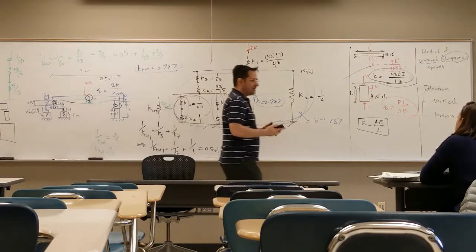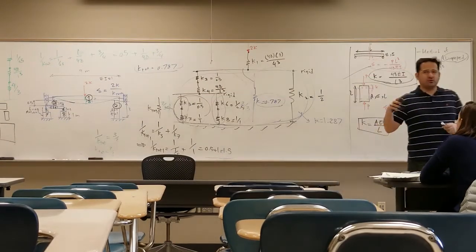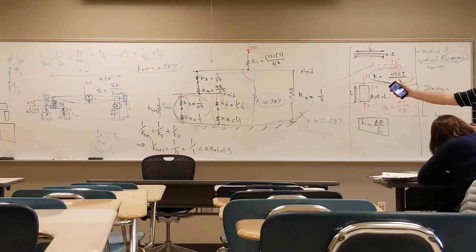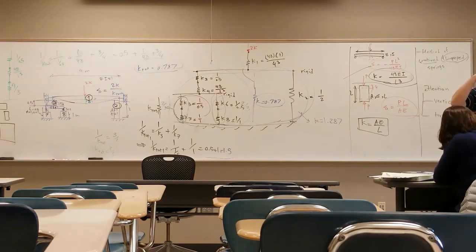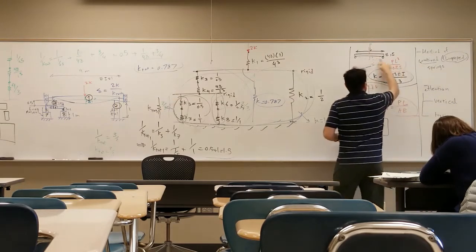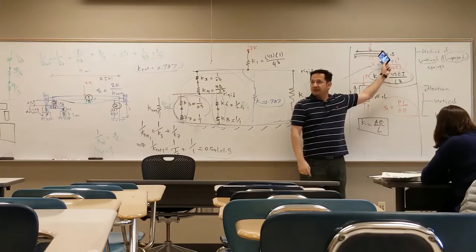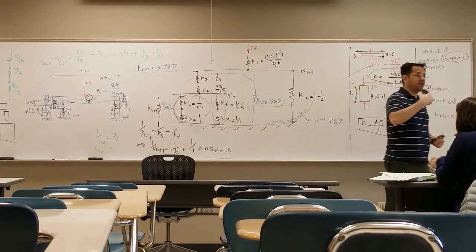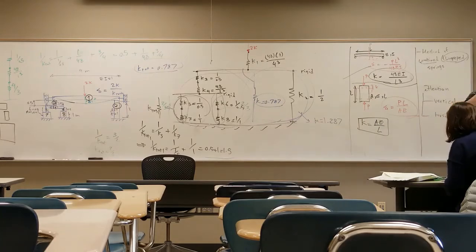Right? And let's say you use software. You go to the software, you model it. What should you get from the software? The same thing, 3 significant digits, as long as the deflection is very small. But what's the assumption for this relation? A small deflection. So when we had the method of double integration, the basic assumption was that the deflection is small.